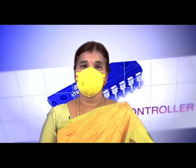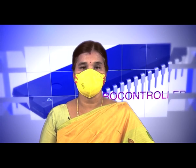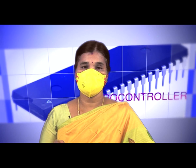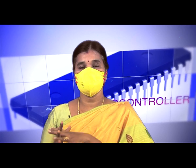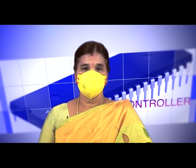Okay. Summary: in today's session we have discussed how to interface the internal and external memory with the 8051. For the data memory and program memory, by setting the EA bar either 0 or 1, we can get it from internal or external. Then, based on the size of the memory, you have to calculate the address lines and interface with the microcontroller. Okay, thank you.